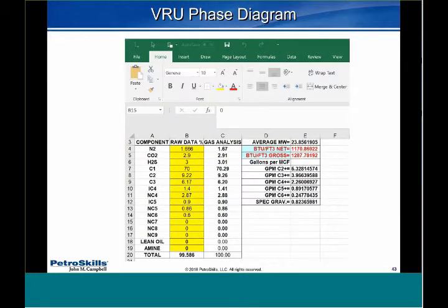I've also included the tool that generated that. You input the gas analysis. I've used this tool for years, and it does some pretty cool stuff. One is it double checks and normalizes your gas analysis to 100. A lot of times there's a few trace components, and you can just go down to C6, put this in there, and it'll do it. For example, this is the sales gas, and it's still fairly rich gas to be using if you're going to use that for a compressor.